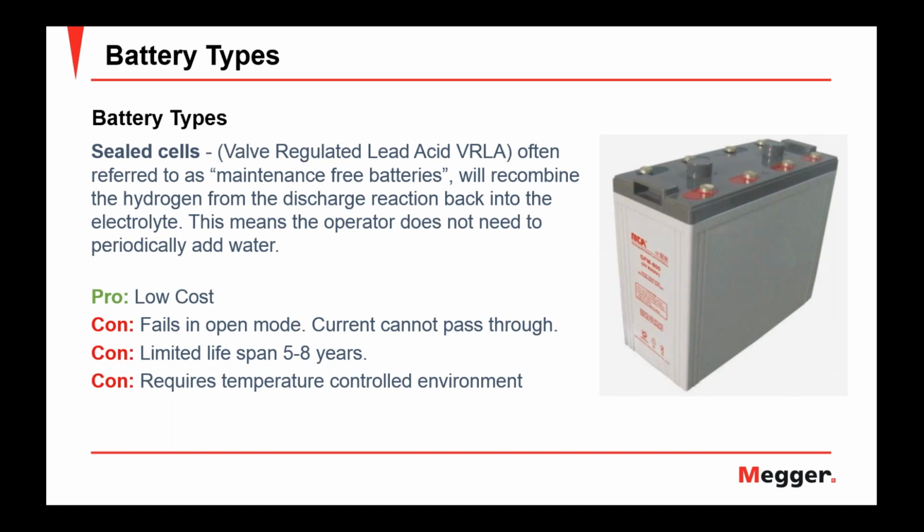They also, because of the small amounts of electrolyte in them, have a limited lifespan. Typically, you get 5 to 8 years, and there are some that are longer life than that, but that is a typical lifespan. And there are some out there that will last you 2 years. Their quality is questionable. The other thing is these type of batteries should stay in temperature-controlled environments because they do dry out, and higher temperatures will make that happen quicker.